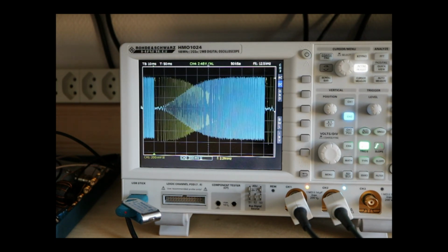then you see that around 1 kHz we have this roll off on both of these filters. These 1 kHz are not precise, because this 96 kHz sampling frequency is not exactly generated. It's a little less, so you have errors here and there, but the principle can be shown.